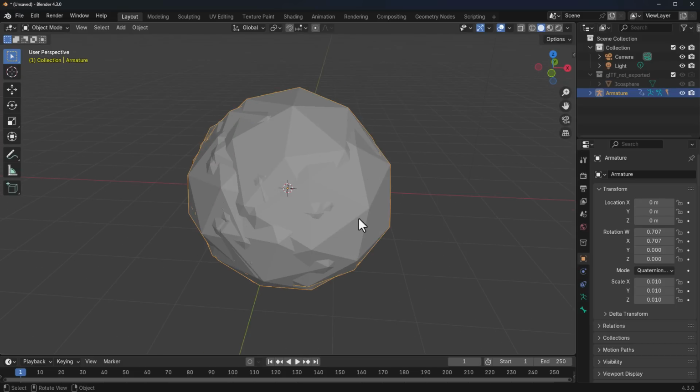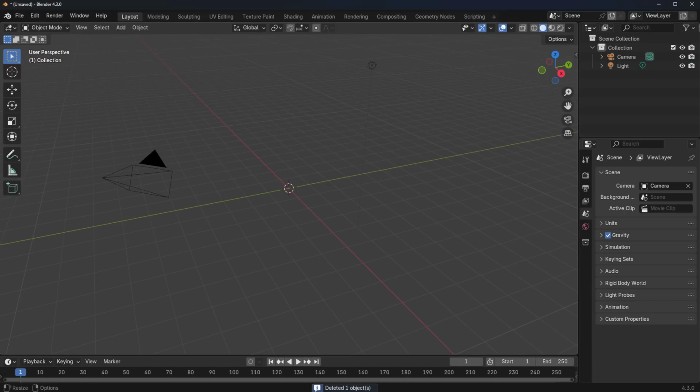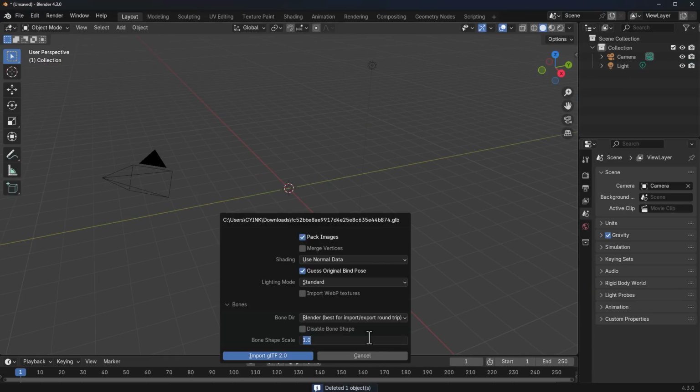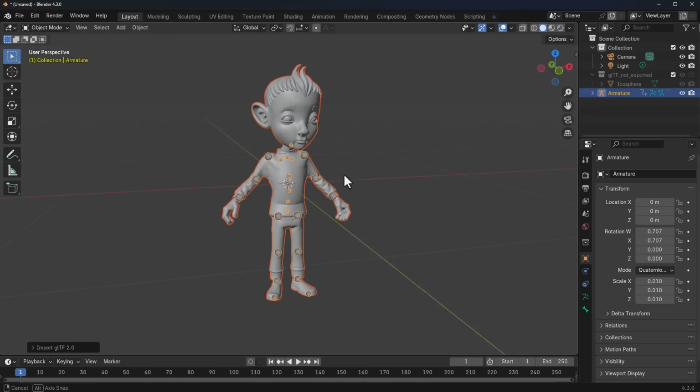We've got large joints. So this is not something that we'd like to do with. So we're simply going to go ahead and bring this back in. So to bring this in, what I would suggest is you set this to 0.01. This might be your best case scenario. Like set this to 0.01, import it, and then this is going to come in with the joints exactly where they're supposed to be without them being unnecessarily big. So we're going to dive right in and you can see it.